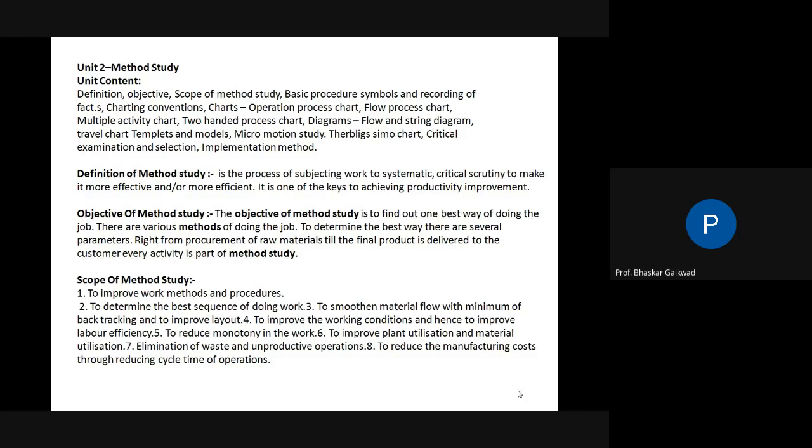Suppose you are manufacturing conveyor parts. So what is the present method? First, you go for blanking, piercing, then the manufacturing of the pin, bush and roller separately, and then we go for assembly. Before assembly, heat treatment should be there. This is the ongoing process in industry. Now you have to study this process and how we can reduce the cost of manufacturing.